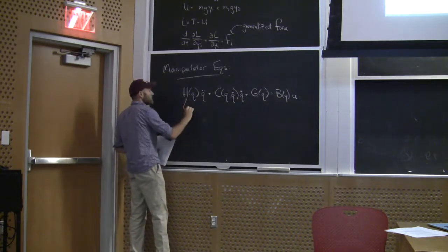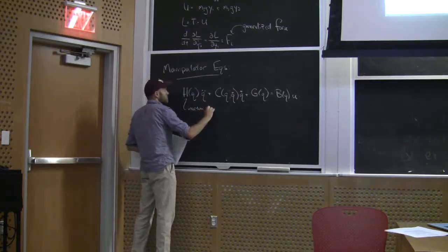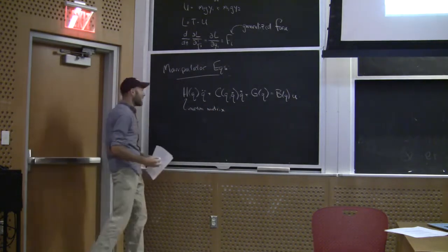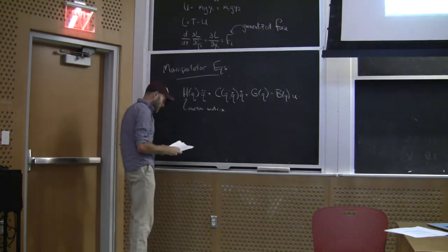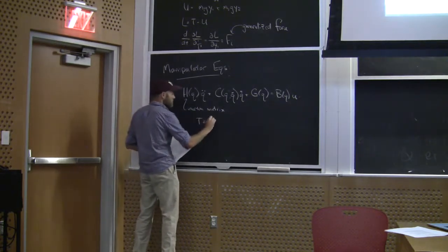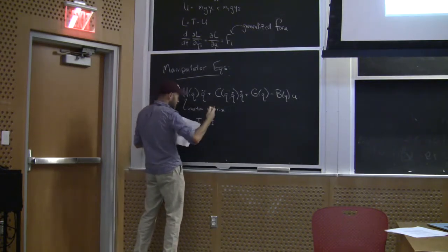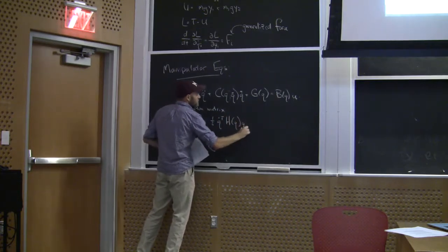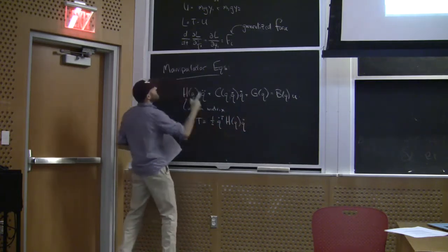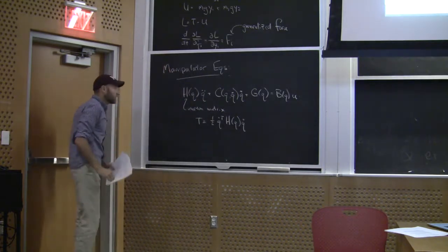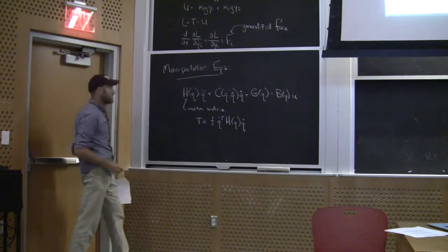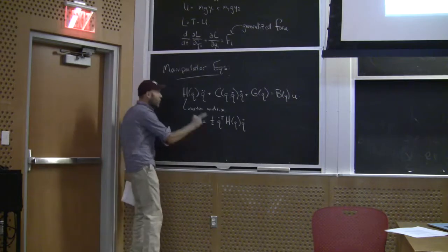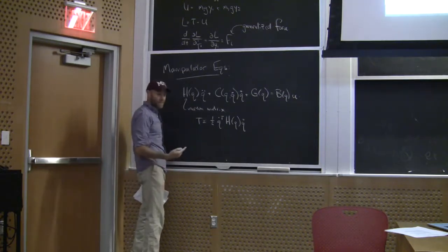So this thing is called the inertial matrix. It has properties that we're going to exploit a lot. It turns out it's clearly related to the energy. I could have written a sort of generalization of the mass. It's the mass matrix. I could have written it as q dot transpose H q dot. It's just like the role the mass plays in that equation, now in a vector-matrix generalized version of it. It depends only on q. It doesn't depend on q dot. That's important structure.